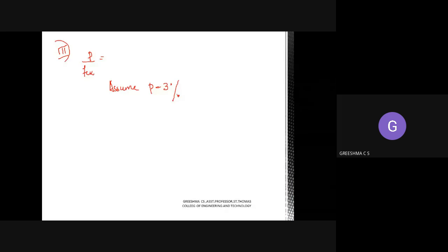If you take 2% or 1.5%, this will not be safe. The column will fail under biaxial bending. You can try p equal to 2% and see what the result is. In most cases this will fail at 2%, so here you need a percentage of 3%.